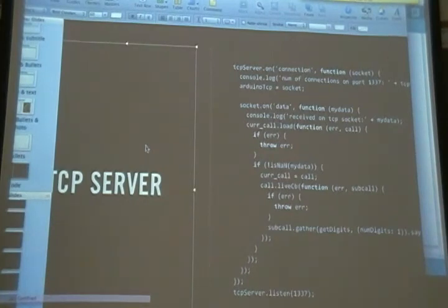So when it's done gathering those digits, it makes a request to your server. And then you have the TCP connection to the Arduino open the whole time, and when you receive the post request, you send it to the Arduino. Yep, exactly. So the node server is really just sitting in the middle. Right. Just because, as I said, doing the web server on the Arduino would be too much.